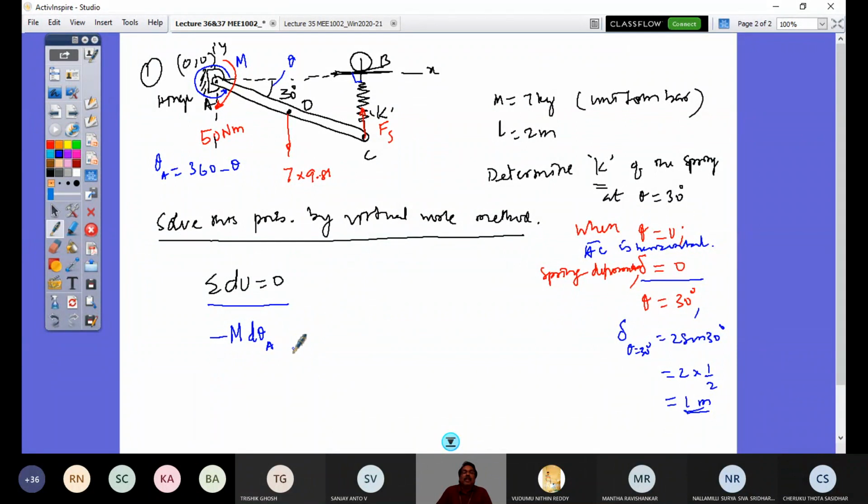This is a very small quantity. And an external force is weight. Weight is acting down, so minus. The convention we always follow in mechanics is: to the right and upward force positive, counterclockwise movement positive. So look at the force and couple directions and follow the conventions to represent them here.